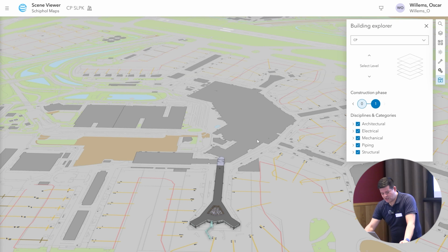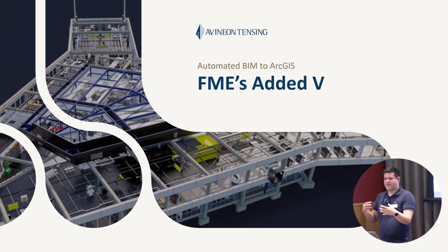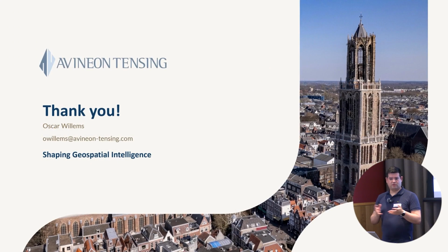And in the end, FME was used to get this data on the map. Before it was just all these separate little BIM files, and now we have one large model where we can walk through and see stuff. FME just schedules it and has an automation: hey, there's a new model, run that one file geodatabase, combine it again, push it back into ArcGIS, and that way we have one flawless process.